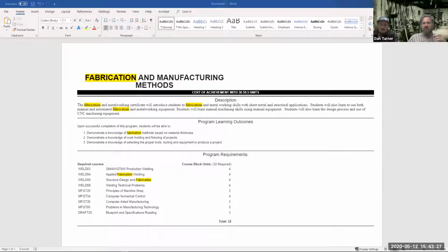So if you're turning to radius or turning diameter, we still have a whiteboard right next to the lathe where they sit there and do the math on it. And then they learn how many thousandths to take off depending on what they're turning down. The big push right now in most educational arenas is the CNC aspect of machining.